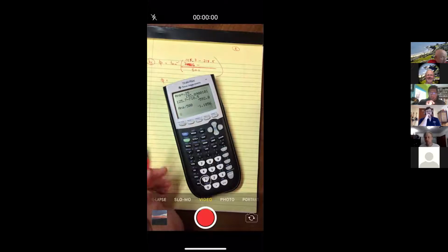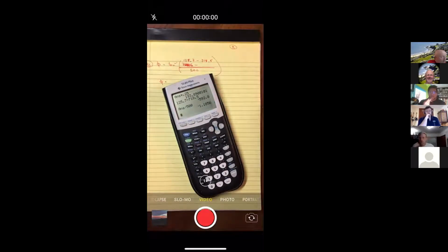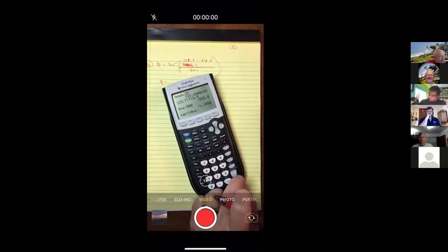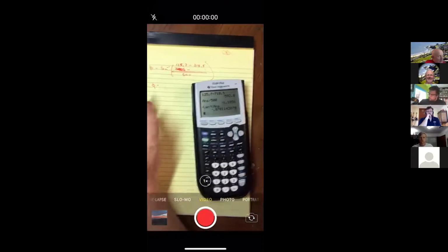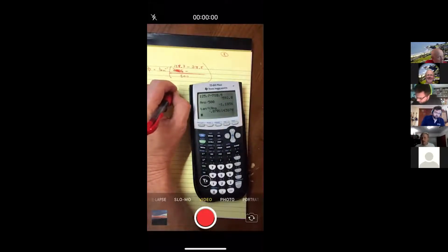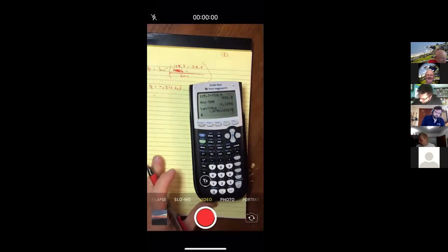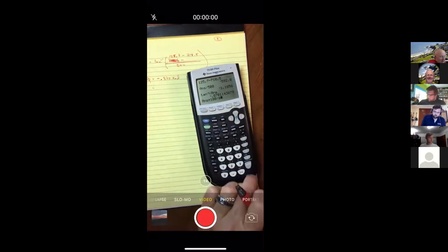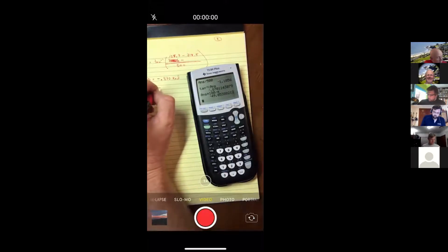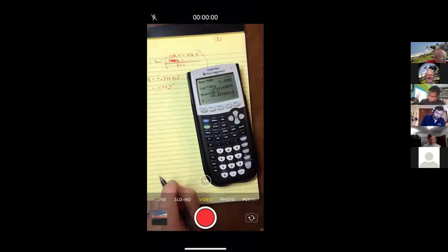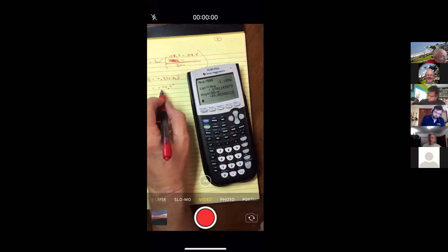Then I'll divide that by 500, and so we have a negative. And that too is the same reason I would say, okay, the current is going to be in front of the EMF. But now let me do the inverse tangent of that answer. And I get negative 0.870 radians. This might be a little bit better in degrees, so let me go times 180 divided by pi. And so negative 49.9 degrees. So the negative tells me then that the current is going to come first.